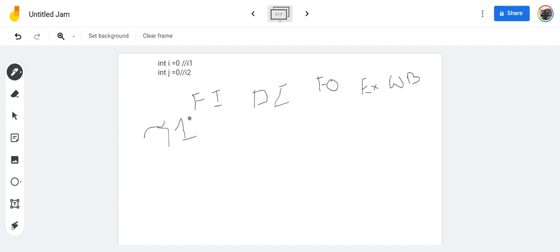So you can see that as the clock starts ticking, that means clock means not the clock which is hanged in our walls. It is the CPU clock. So with the clock starts ticking, the first instruction, that is instruction 1, is fetched into the memory, right? Now in the first clock cycle, you can see that other segments of the CPU are kept idle. That means there is nothing to do. Now, when the next clock cycle starts, that means clock cycle T2, before the beginning of clock cycle T2 and at the end of clock cycle T1, instruction 1 is already fetched into the memory, into the processor, sorry.